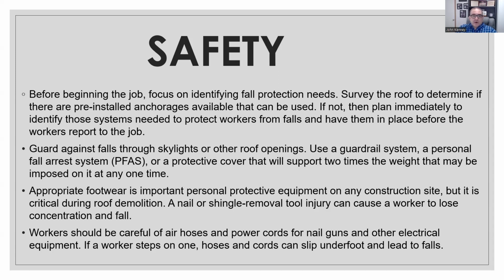Appropriate footwear is important. Personal protective equipment, PPE, is needed on any construction or roofing site, but it is critical during roof demolition. Nail or shingle removal, or a tool injury, can cause a worker to lose concentration and fall. Again, that means sneakers are not acceptable during a lot of processes. You can use certain slip-resistant, sneaker-type soles when you're doing single ply roofing. Again, OSHA has all these laid out. Go check for what's appropriate in your area for the type of work you're doing.